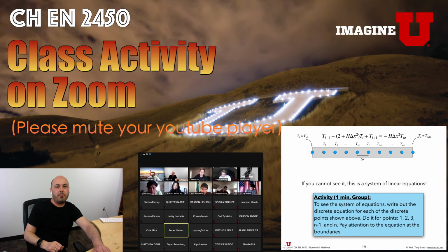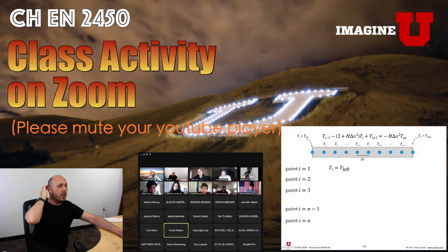Okay, so let me show you how I would do this. At point 1, T1 is simply equal to T left. Now remember, we didn't define T0 when we set up the problem. There's no T0. We started with T1 to Tn. You invented a T0. We're going to invent a T0 later when we talk about Neumann boundary conditions, but right now we're not, okay? So T1 is T left.